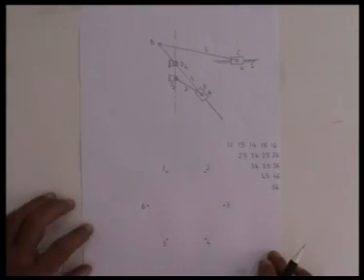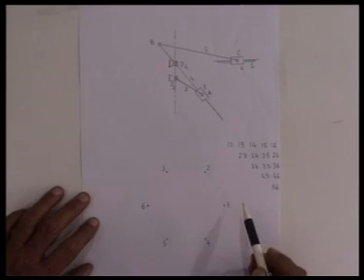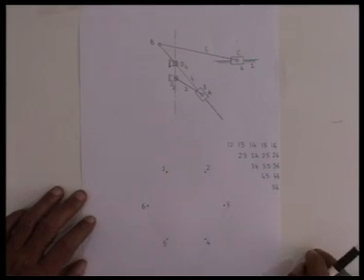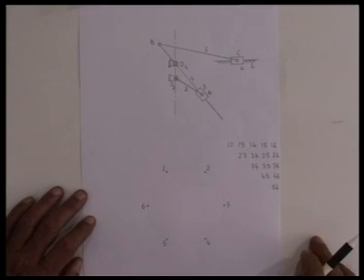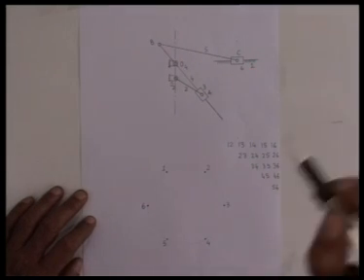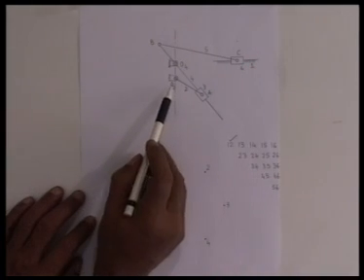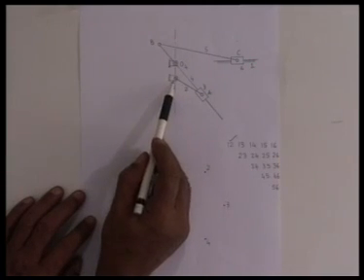At the second stage, let us now try to locate all those relative instantaneous centers which can be easily obtained by inspection of the kinematic pairs. For example, 1, 2 is easily located at the revolute pair between link 1 and link 2, that is at O2.